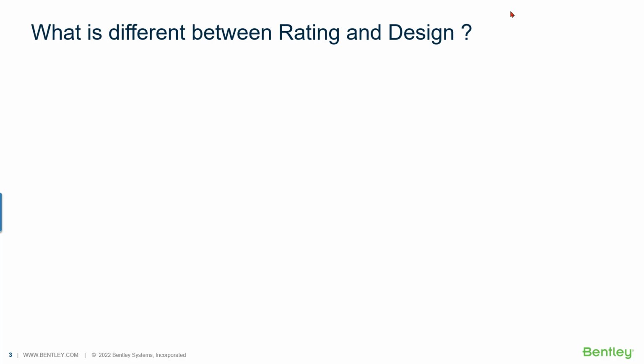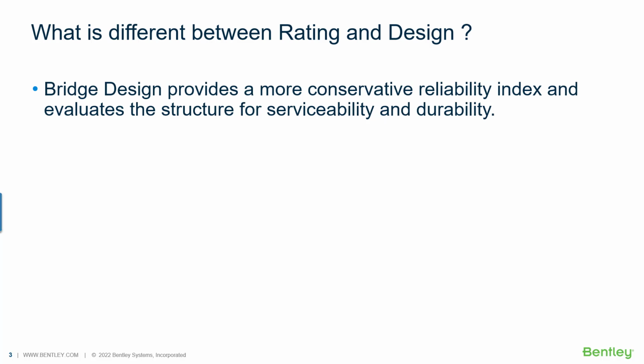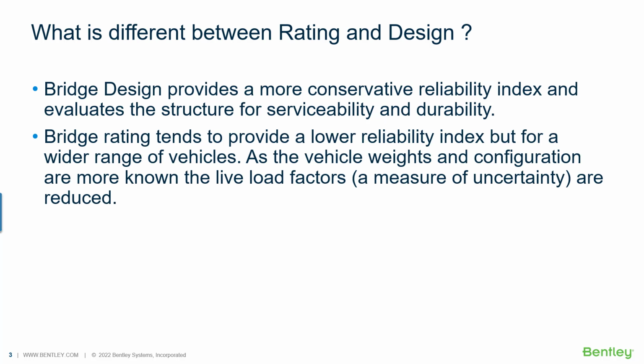You may wonder what the difference is between rating a bridge and designing a bridge. In bridge design, we provide a more conservative reliability index, and we evaluate the structure for serviceability and durability. Bridge rating provides a lower reliability index, but for a wide range of vehicles, so it's precisely for different types of vehicle. This is because the weight and the configuration of the live loads are more known, so the measure of uncertainty is reduced.